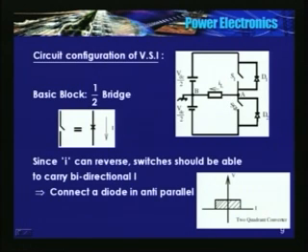So that's the reason you should be extremely careful in operating a voltage source inverter. Two devices should not be on at any given time. In other words, there should be some delay between the gate signals applied to S1 and S2.